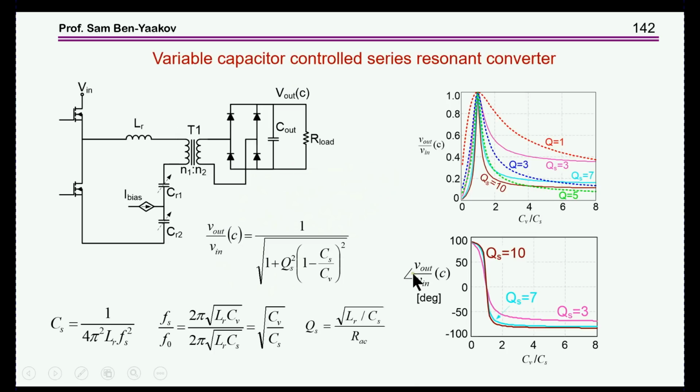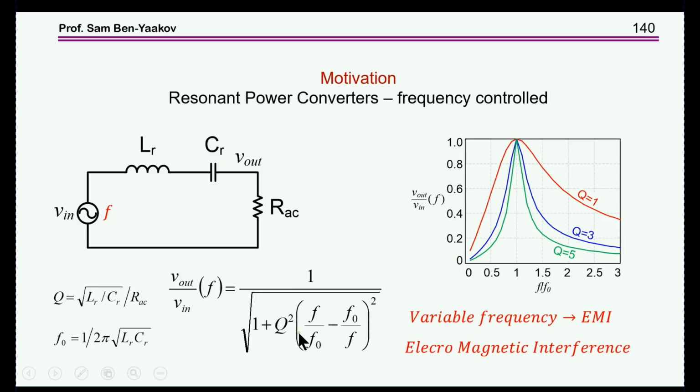The equation that I've shown you assumes a linear circuit. Assume that there is some resistor, a rectifier, plus a capacitor filter, plus a load that is nonlinear. And you cannot do a phasor analysis on it. To do a phasor analysis, you need to have a linear circuit.